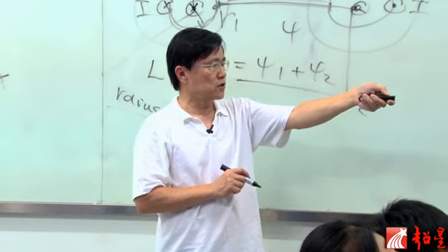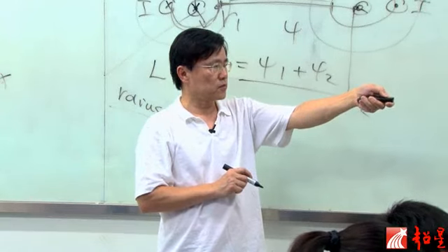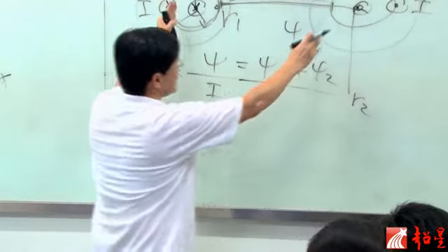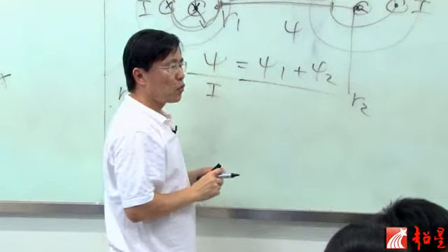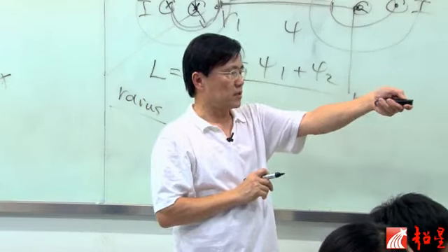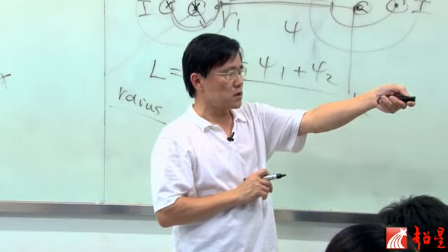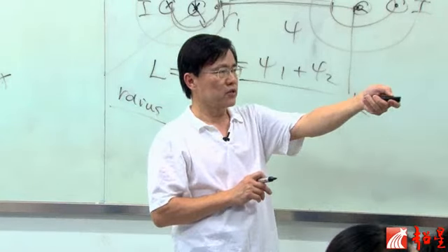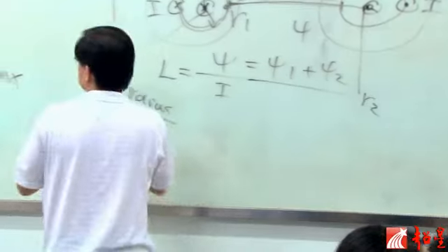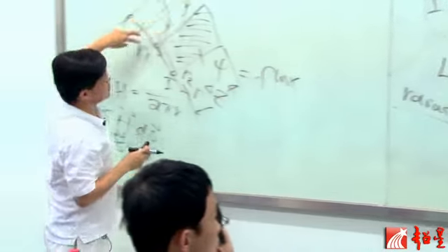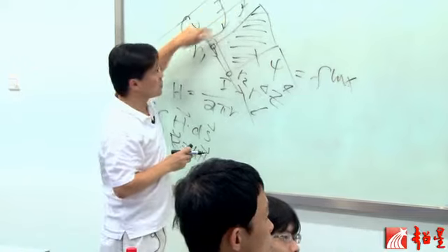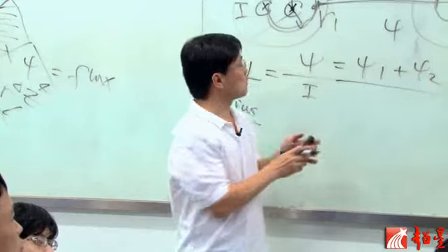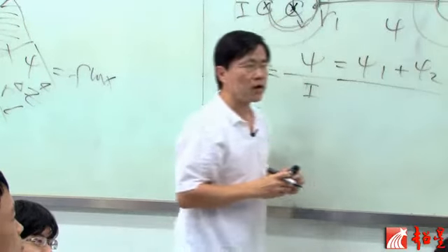Then you take the ratio of these two. Then you can express inductance this way. So the inductance between these two wires can be expressed by this expression. And the assumption here is that Z is equal to 1. That will give you per unit length inductance. Basically, the length here is 1. So that's how you can get the per unit length inductance of these two wires.